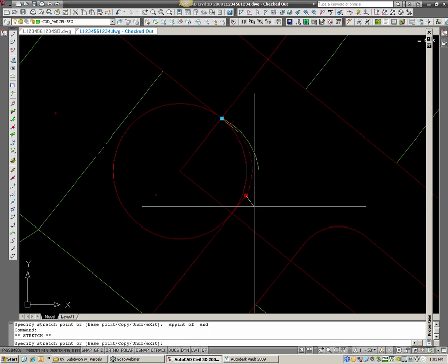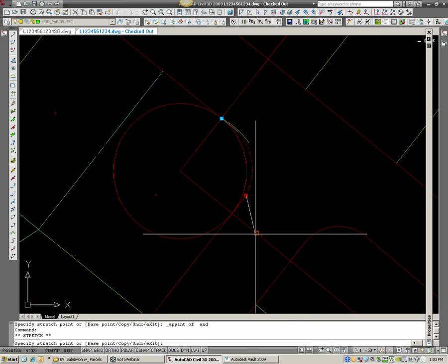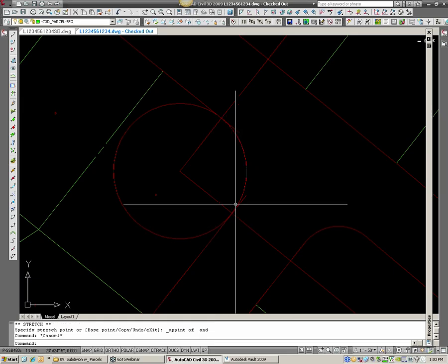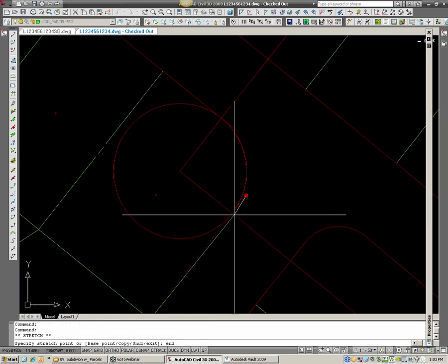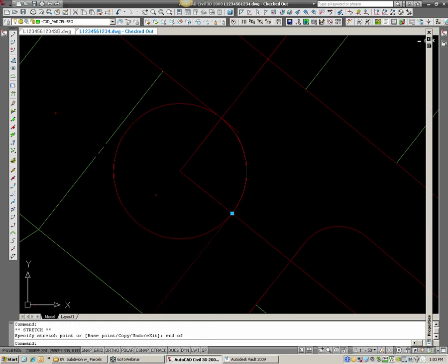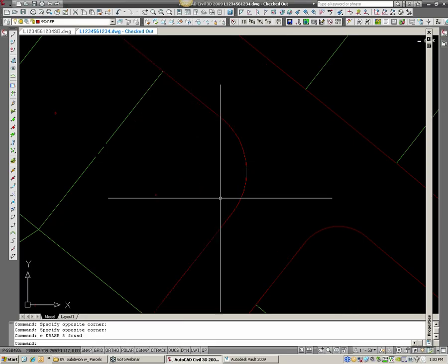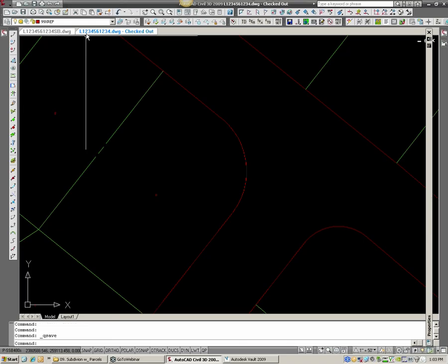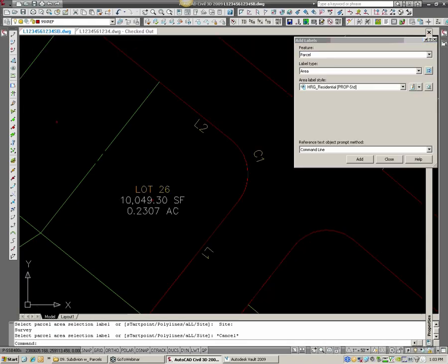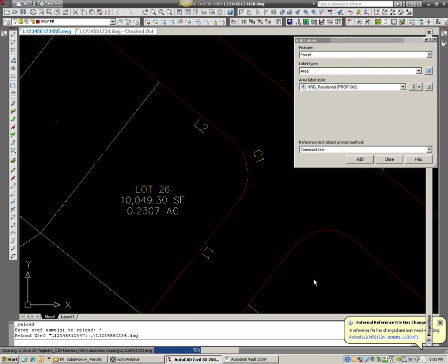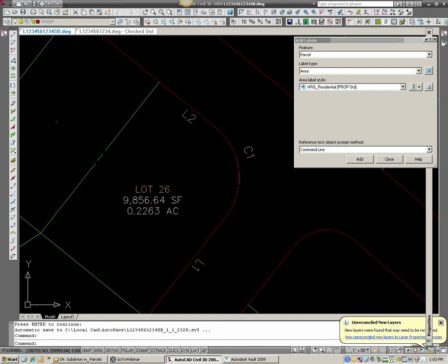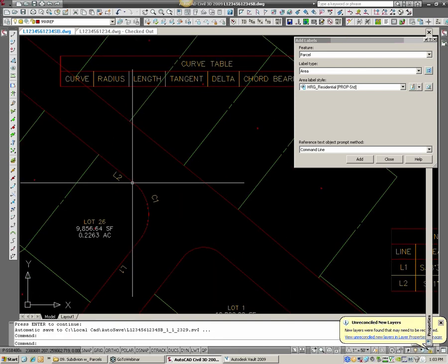Okay, grab that, edit that arc, and then once I'm done with that, I need to grab the segments and drag those back, grab those back, and then I can delete this tracer line work or my construction line work. I can hit save and go over to my drawing where everything's labeled. I can hit update, and you can see everything maintains and stays updated.